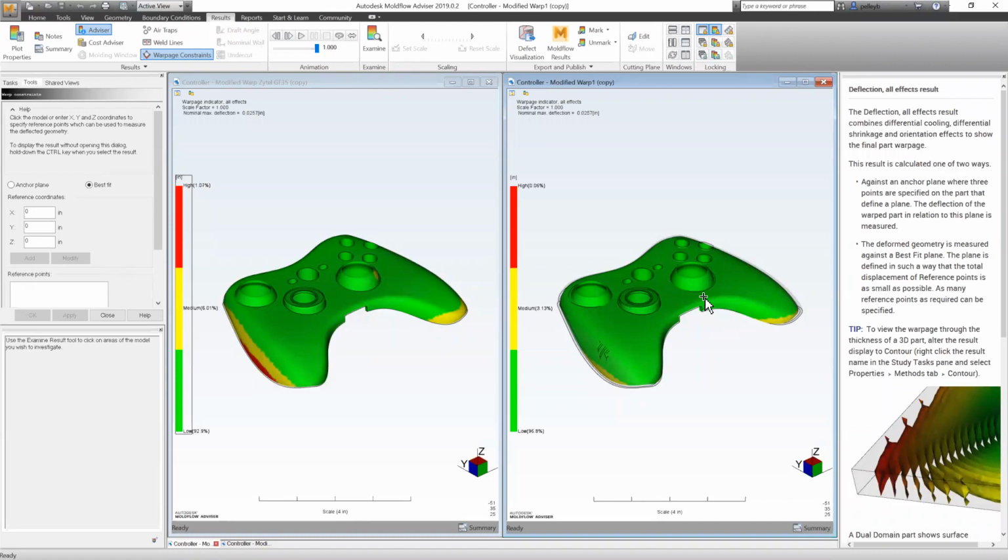Always consequences with our design choices, and this can be an aggravating one. Warpage is definitely hard to combat when you get to manufacturing. Quite often it will mean economic losses, longer cycle time, post-mold shrink fixtures, all that stuff you don't want to have to do. With that, I'll turn it back over to you.